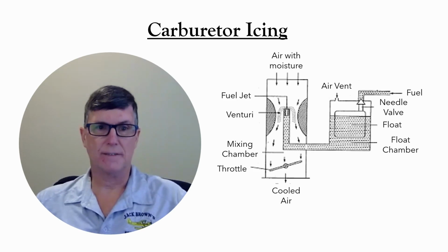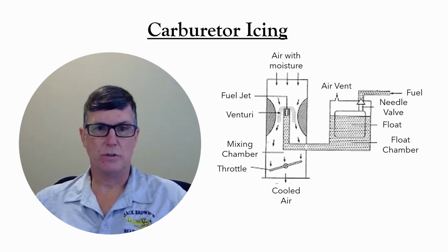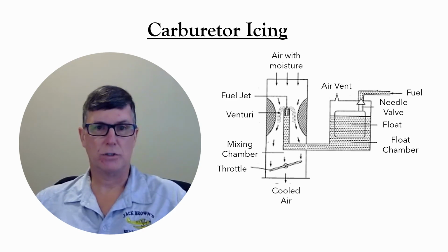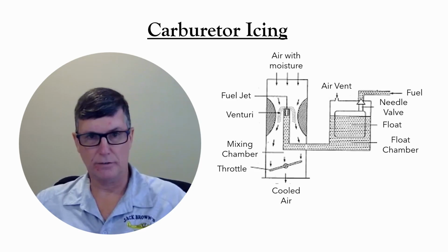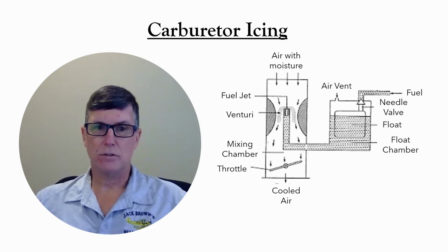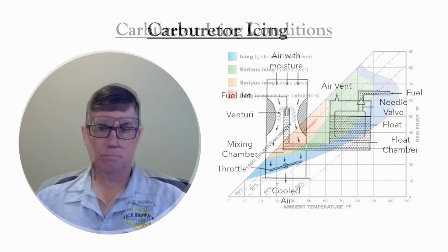Similarly, ice forming in the venturi will make that venturi opening even narrower, and it will cause more fuel to flow in, making a richer mixture, which can lead to even more carburetor icing. So, in other words, once ice starts to form, the problem is likely to get worse.